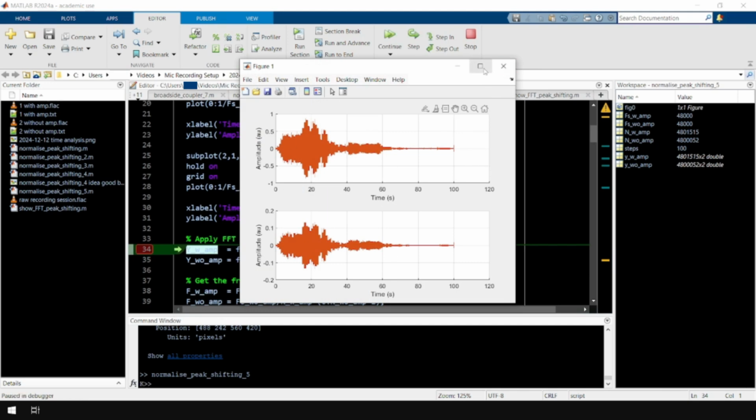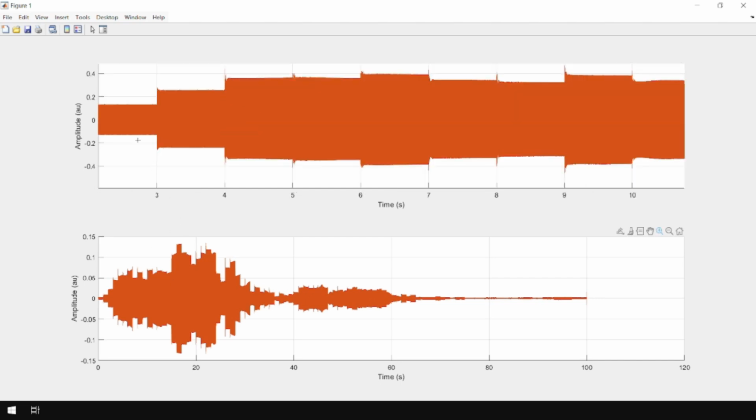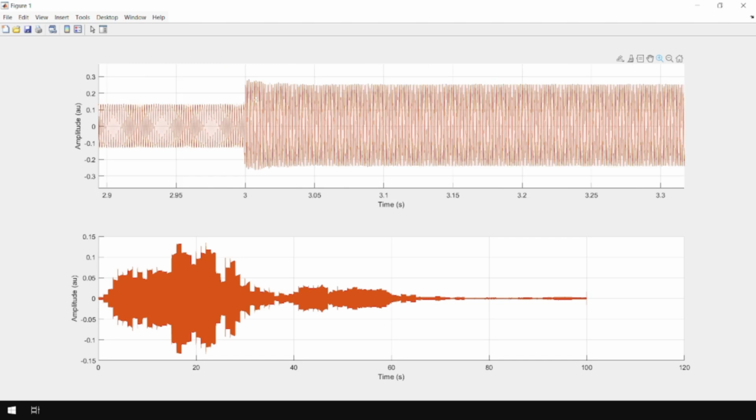So you can see the waveforms here. Now immediately we can see these spikes are occurring when the frequency shifts, and there's also some amplitude weirdness that you can see that's rising there and that's rising there, where it should be a perfectly consistent amplitude. If I just zoom in, we can see that there is actually a settling time.